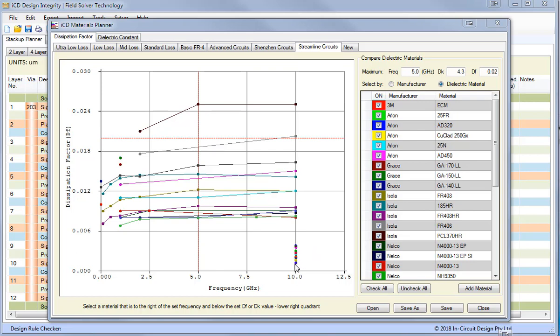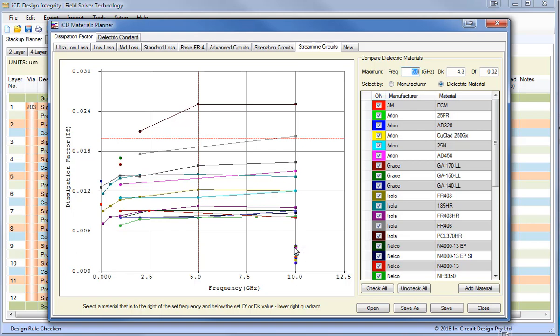And you can see here we have a lot of very low loss materials, which are Rogers, basically Arlon, and we move up the line, there's a few others like Nelco, which is fairly low loss as well, and you'll find there's some Isola and TUC, Taiwan Union Company, more Isola, etc., up to the basic sort of FR4 type materials. So if you're looking for a basic sort of material, you may say, okay, I want 0.01 loss, and so you select a material that's close to here. So here an Isola FR408HR would be the ideal choice.